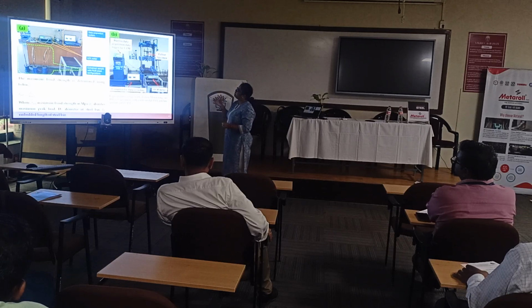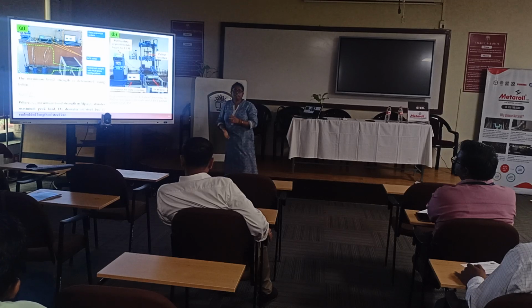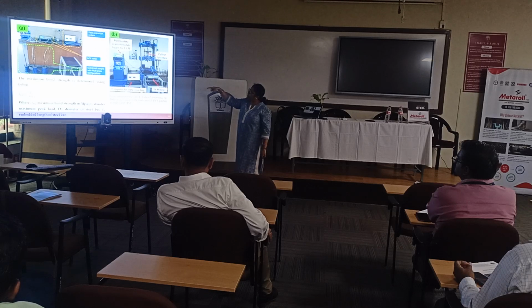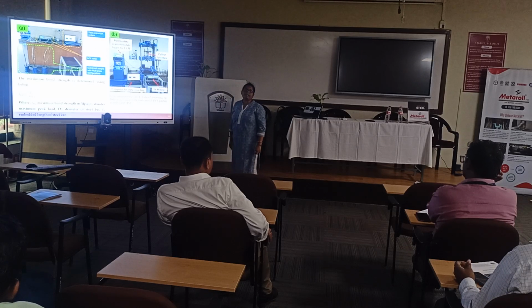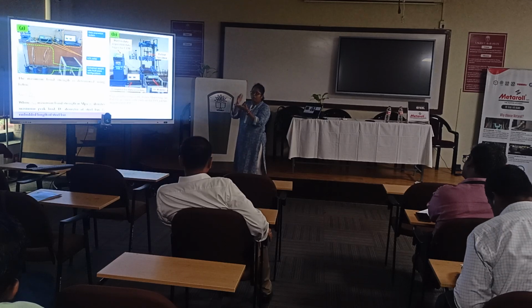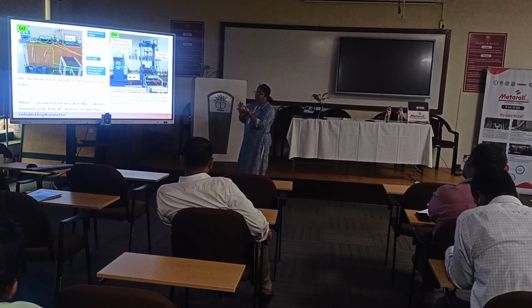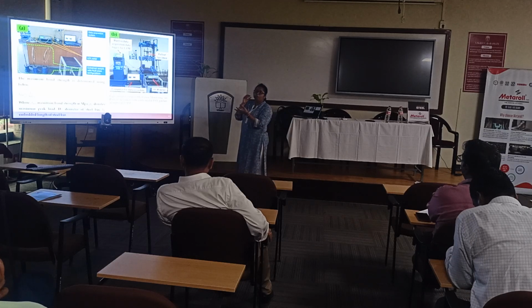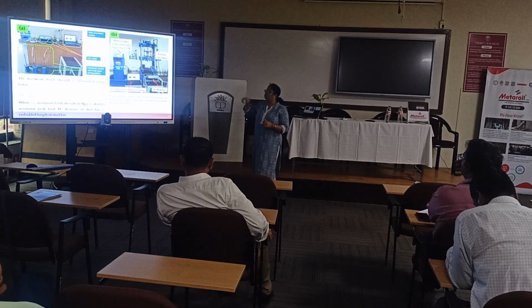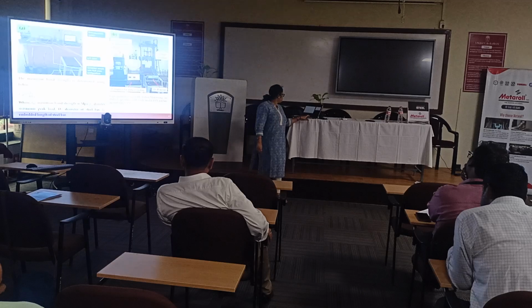With the application of tensile pull, the steel bar will come out, and we measure the slip from the LVDT, as well as the signatures from the LCR meter. Since it is a stress control UTM, what we do for strain based control is that for every displacement level, at every 10 mm displacement interval, we take the measurements, and with the measurements we also get the signatures from the LCR meter.